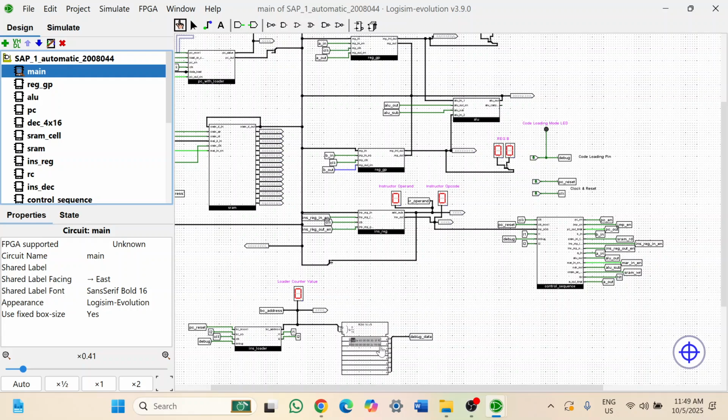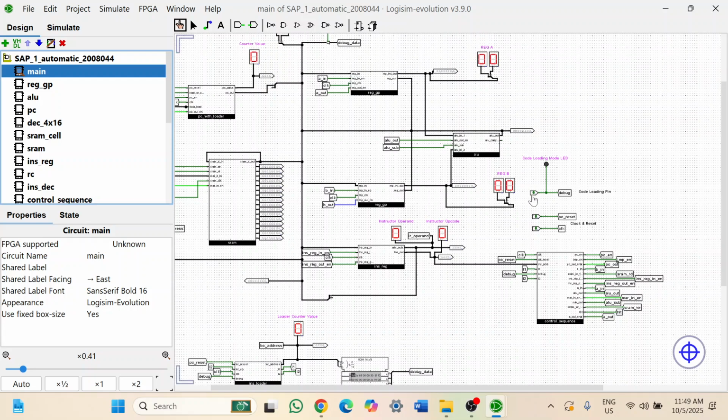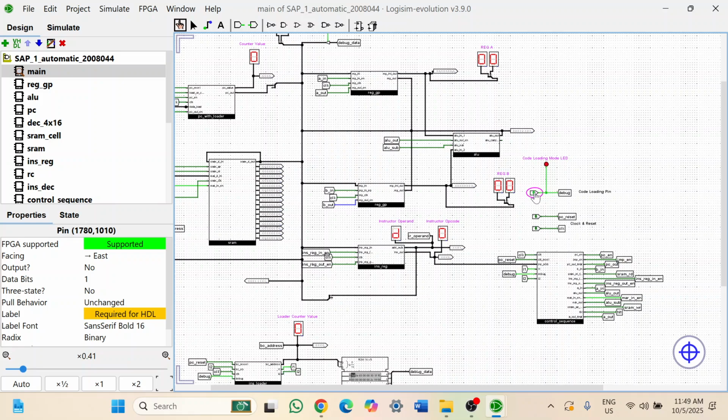To transfer this instruction and data to RAM, we activate the debug mode, reset the program counter to 0, and apply clock pulses. Each of the 16 RAM locations requires 2 pulses, one to set the address and another to write the data, totaling 32 pulses. Upon completion, the RAM is fully populated with the program and data, ready for execution.